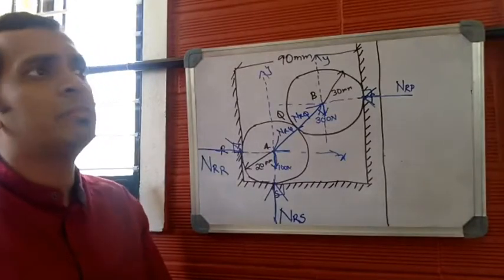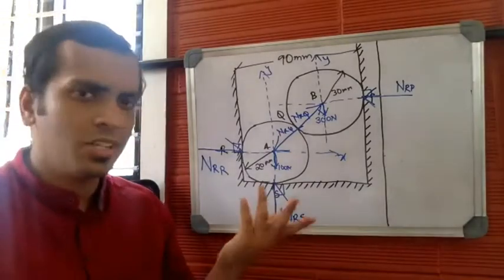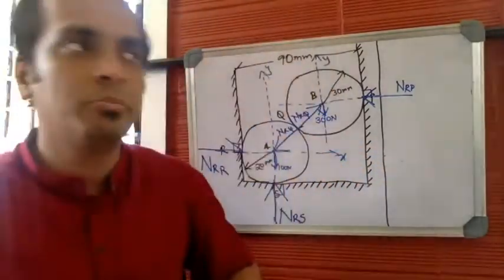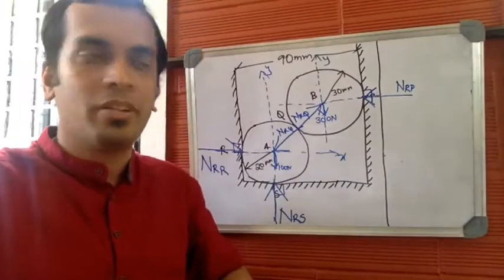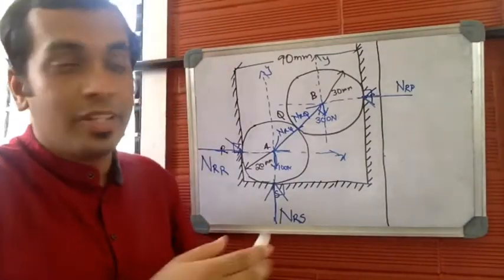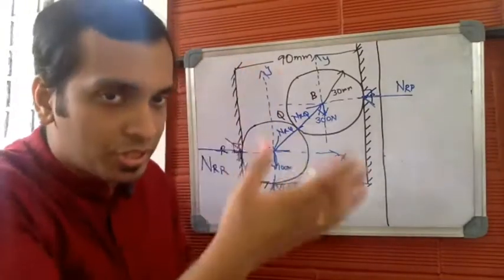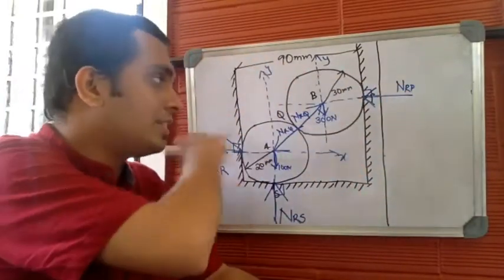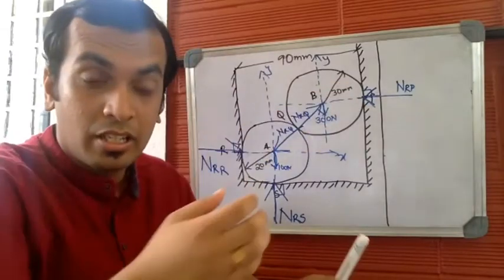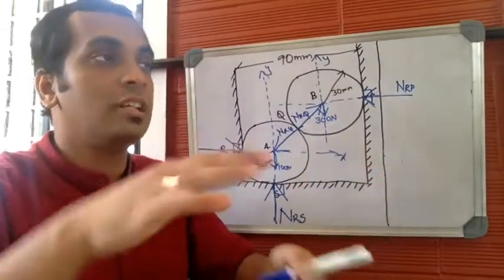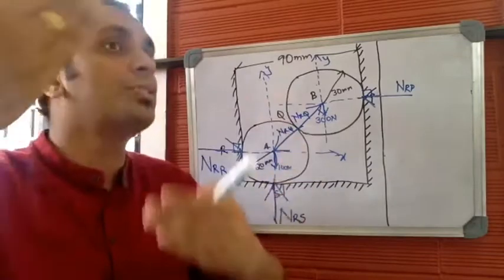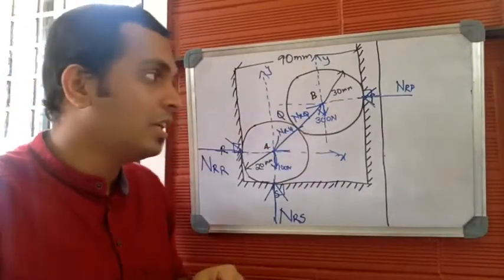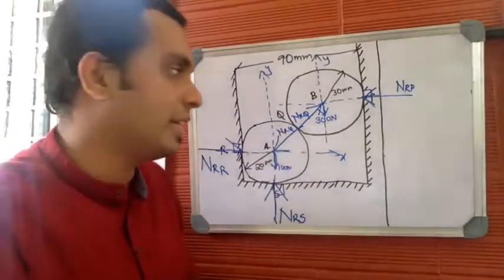Now, step number 4 is to mark the tension along the string. There are no strings given here in the problem, so you can eliminate step number 4 and directly go to step number 5. In step number 5, we reproduce only the coordinates and forces systematically by bringing all the forces to the center and drawing it separately. What you draw in step number 5 is the free body diagram. So this is the 5th step in drawing the free body diagram.